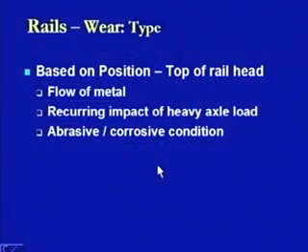Then the next point is that there can be an abrasive or corrosive condition which may get induced. Abrasive or corrosive conditions are two different conditions. In the case of the abrasive condition, it is required that there should be some abrasive charge which helps in the removal of the material due to the rubbing action of different things taking place. Now, when we have different types of material rubbing each other,